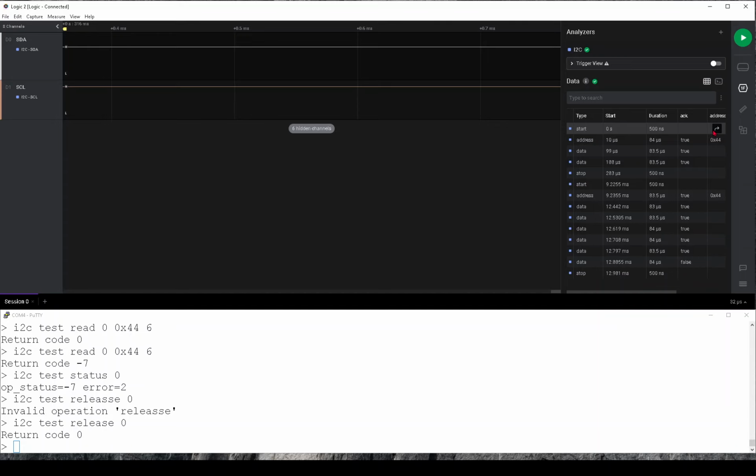Resetting the MCU would be one choice if that resets the other hardware on the board. Another possibility is I have a GPIO connected to the reset pin of that sensor, and that way I could reset that sensor on its own. But it is always good to try these things and try odd things and see how these devices behave, because you'd rather know early than find out about it late.